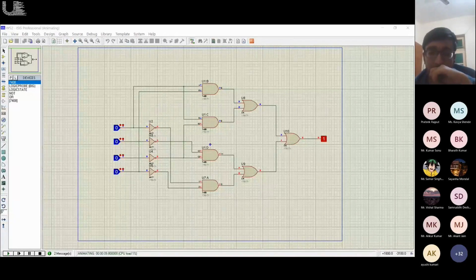And if you remember, the question was, 1 was there in the K map. So we had 1, 3, 4, 6, 8, 9, and some more terms. 0 was a don't care in the K map. So as you can see, we don't care whether the output is 1 or 0. We are not using this output anywhere when it is 0. So that's the concept behind don't cares. We don't care for that input what the output is. It doesn't matter to me whether the output is 0 or 1. But what I cared about is 1, 3, 4, 6, 8, 9, 11, 13, 15.